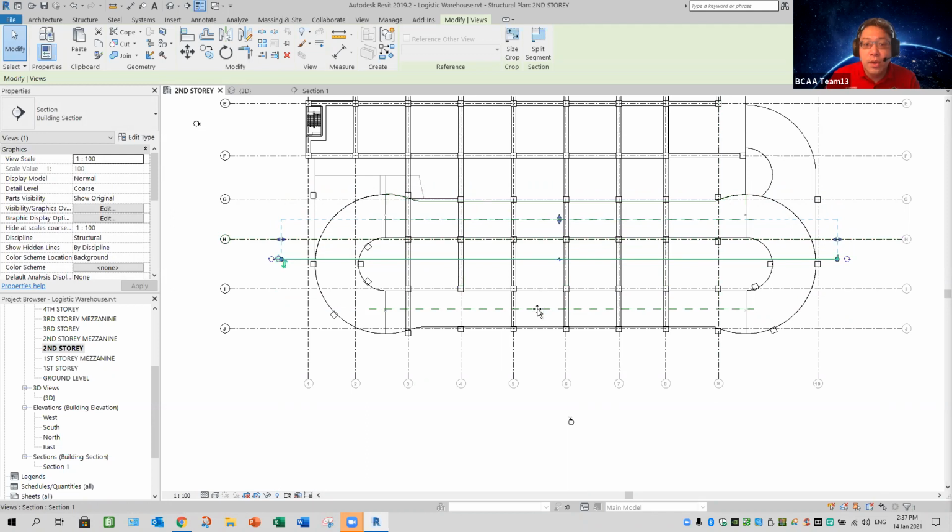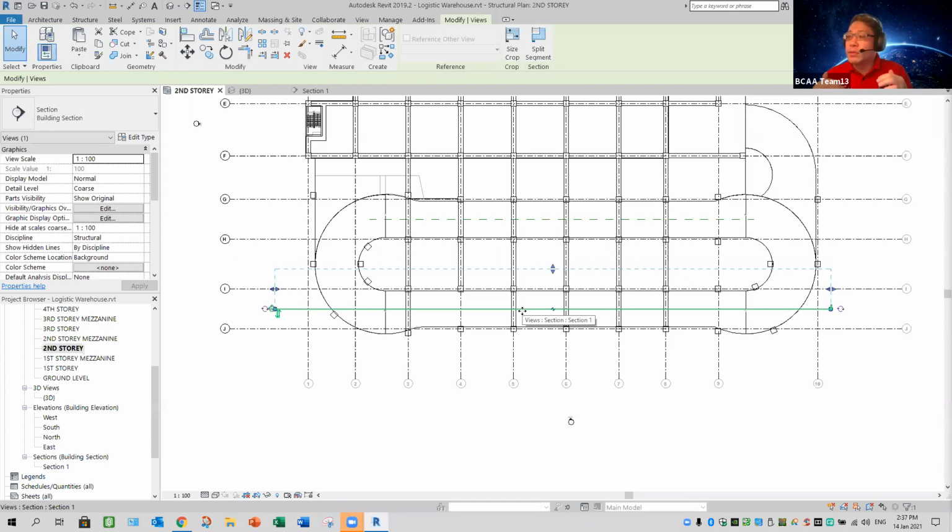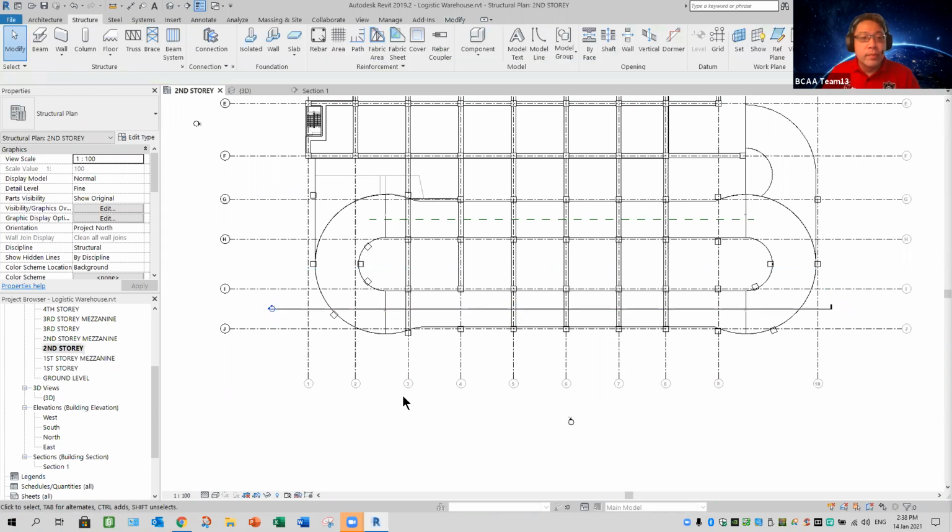This is what you want to adjust. This is important because in 3D they don't allow us to do the adjustment. So we've got to base on this section view to manipulate your component movement. Right? So section view is not just to disclose or share with your contractor or to show things that are hidden. Yeah, we can use section view for our modification purpose also. All right. Any questions for that? The RAM. I mean for the beam.